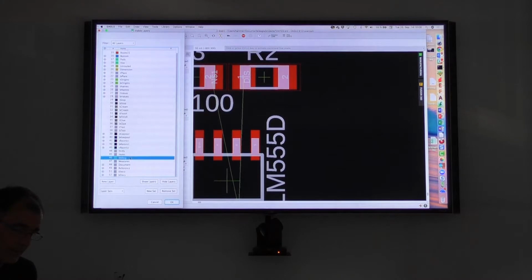Then the important one, it's milling. So if I want to have milling contours, some openings, cutouts in the board, I would draw this in the milling layer. So the board manufacturer knows, okay, I have to mill out this area. That's something that also works now with the board contour detection. If I draw something in the milling layer, you will see that Eagle recognizes this.